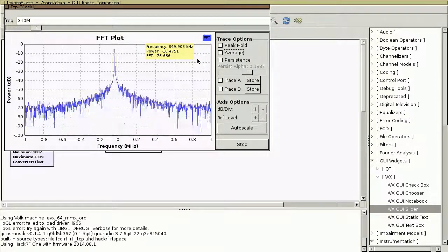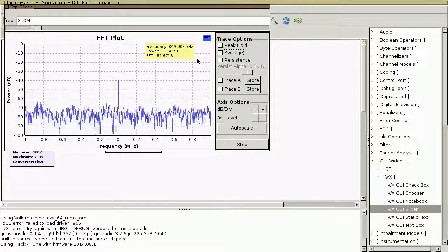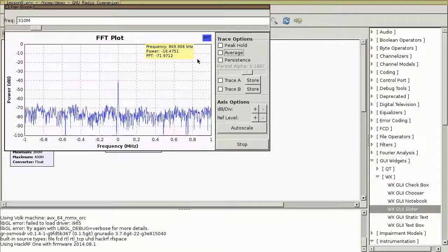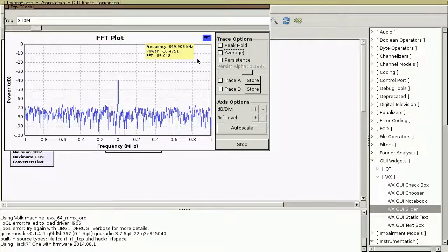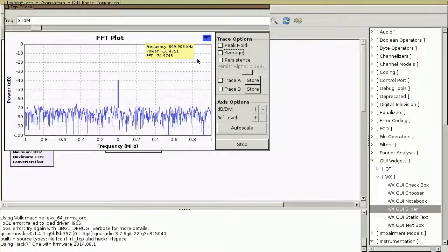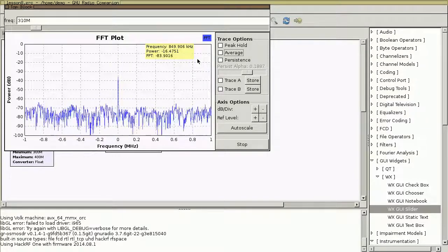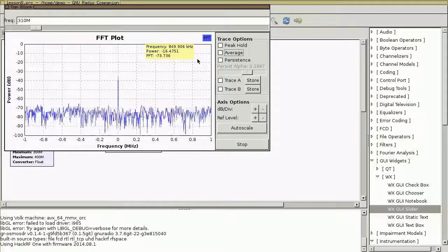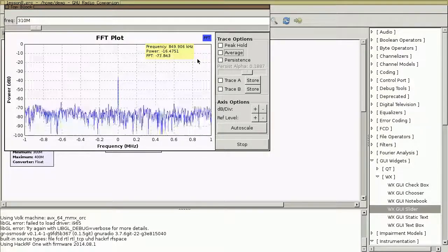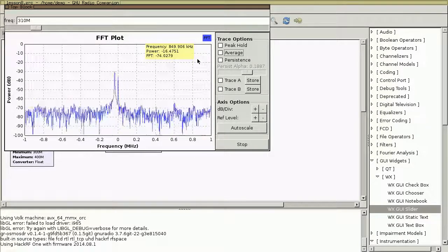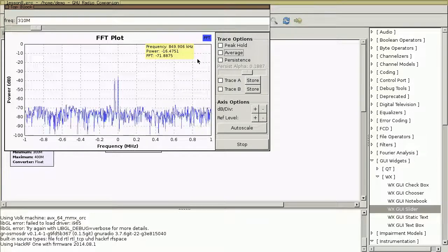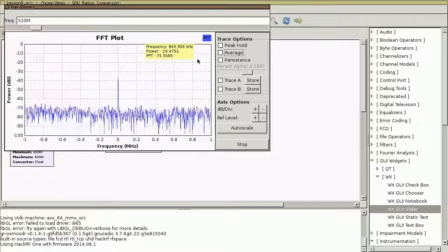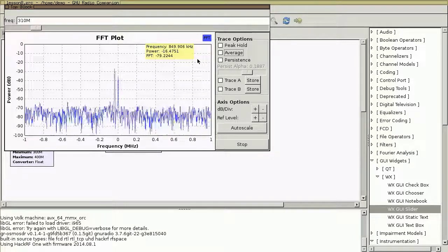If I hold it right next to the antenna of the receiver, we're actually getting some other frequency components because we're distorting a little bit, because we're up pretty close to 0 dB. But if I hold it at a more reasonable distance, like a meter away, then I'm at somewhere around -30, -40 dB, and we seem to get a nice clean signal for as long as I hold down the button.